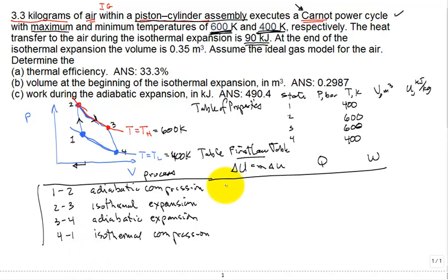So I would put right here my mass, then I would put U2 minus U1 for that. Okay, and then my mass, and then might be U3 minus U2. And then the mass times the change in the specific internal energy, U4 minus U3, and then the mass, you've got to go slow right here because the final state after the end of the process going from 4 to 1 is U1, not U4. Did I mess that up? That's U3 minus U4. There you go. Let's take a look. 1 to 2, 2 to 3, 3 to 4, 4 to 1. Yeah, I think that's right.